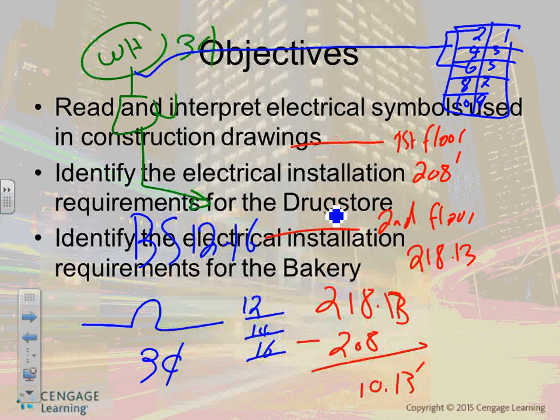There are relays and other kinds of things; they're sensors, they sense the voltage. When the voltage is lost, they go start the generator. Typically, guys, they keep the generator hot because they have a heater, so it's like your car. Because the diesel engine generator is kept hot through a jacket heater, the signal is sent instantly, the generator starts, and within 10 seconds it picks up the load.